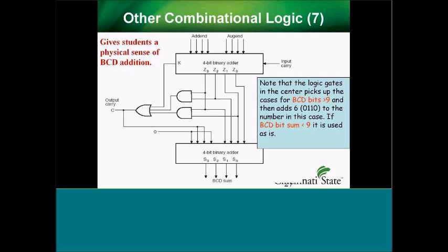Last bit in adding is BCD adder. And so basically, if you take a 4-bit binary adder up there, which I've driven just in chip 4, I've got input carry, and that K is an output carry. Then I put it through an additional adder with a little bit of glue logic in there.